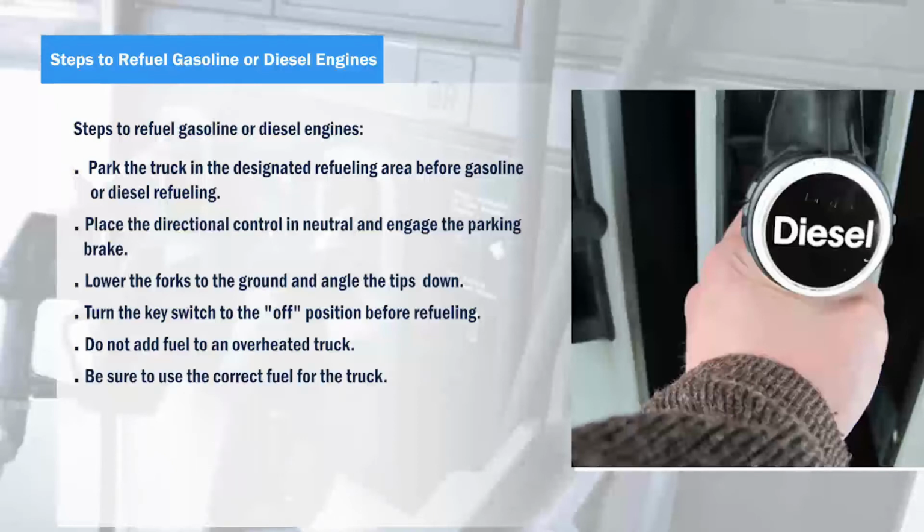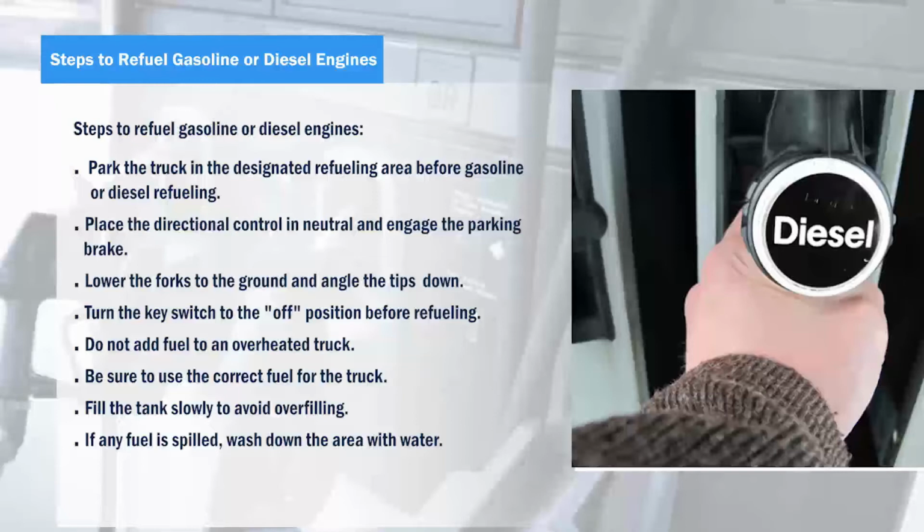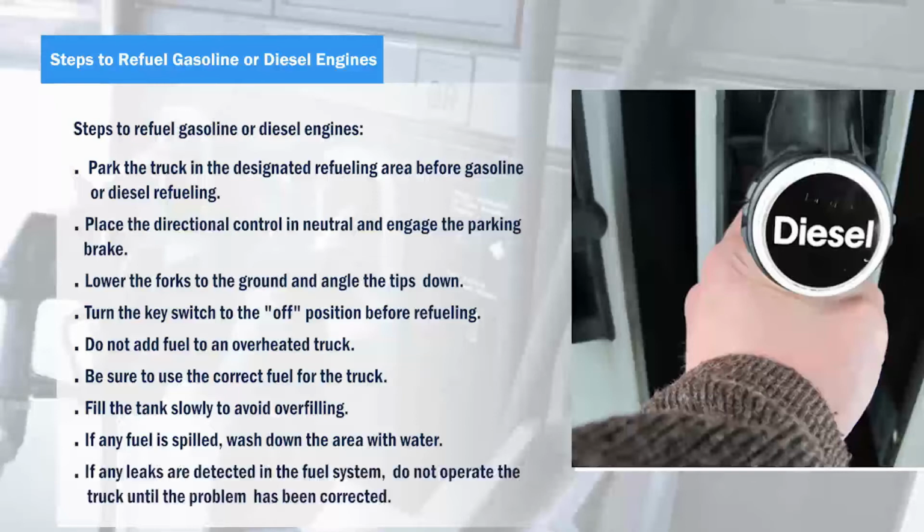Be sure to use the correct fuel for the truck. Fill the tank slowly to avoid overfilling. If any fuel is spilled, wash down the area with water. If any leaks are detected in the fuel system, do not operate the truck until the problem has been corrected.